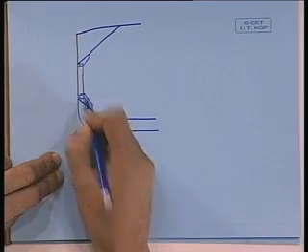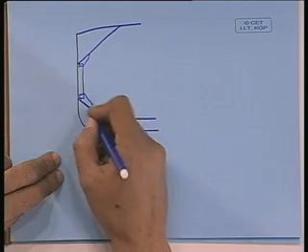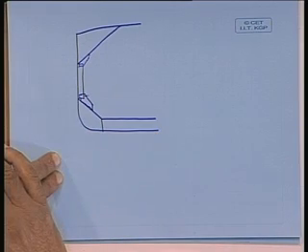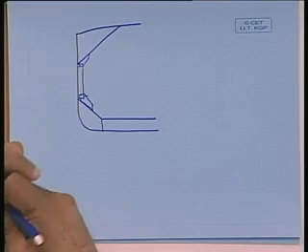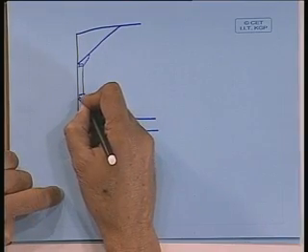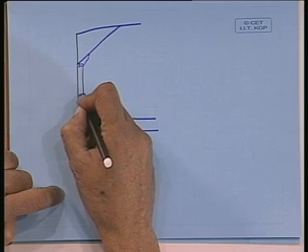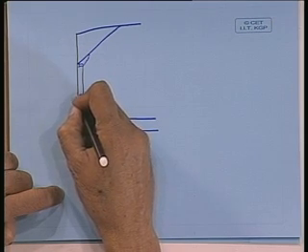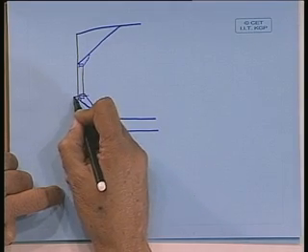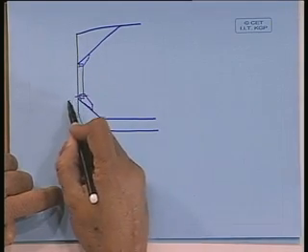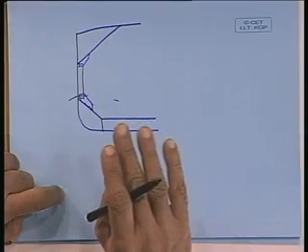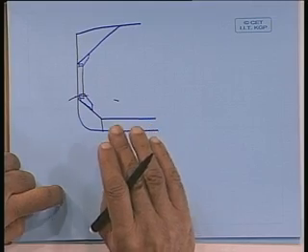Okay. Now, in the majority of the vessels, they found that the crack started from here, and this crack and the bracket progressively propagated to the stiffener here, and then finally to the hull, opening it to the sea, and therefore from this side the water entered and slowly flooded this part.